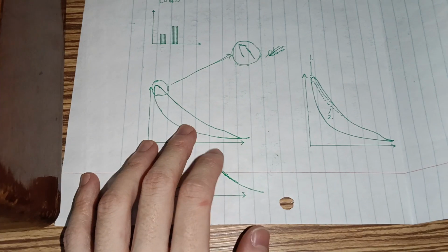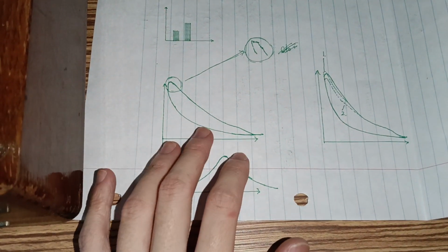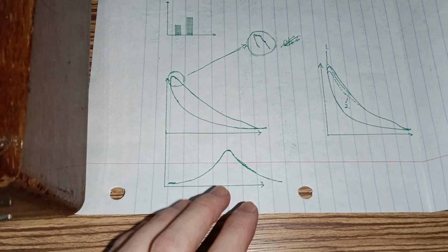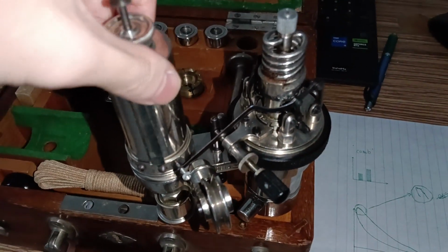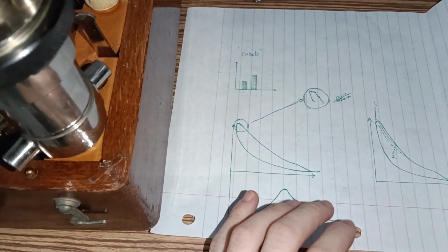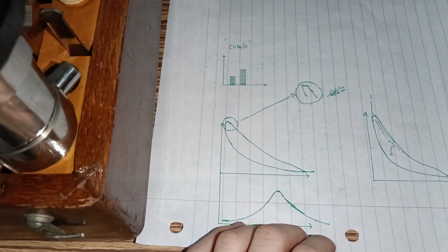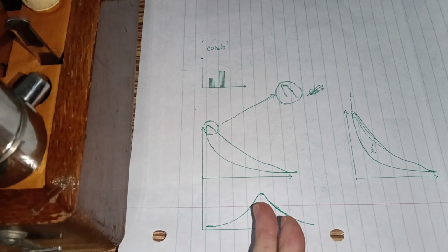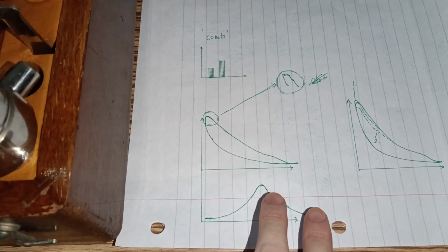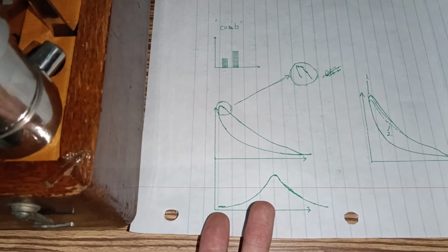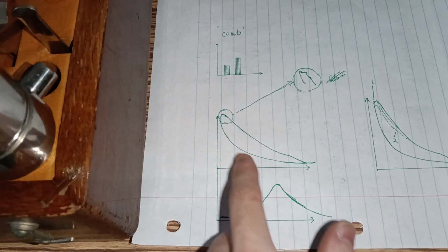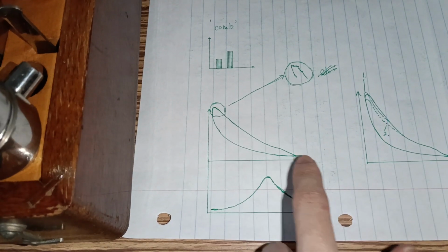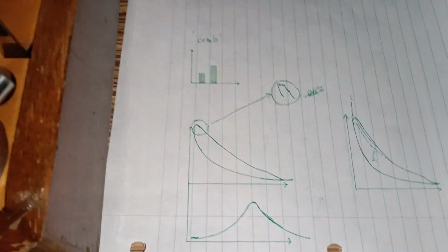So these two are the standard indicating diagrams. The difference between those two is the movement of this cylinder and the movement of this pencil here, which are 90 degrees out of phase between these two diagrams. So you can actually imagine if I fold this one and move it to here, or swap this part to here, you can get a closed loop diagram like this.